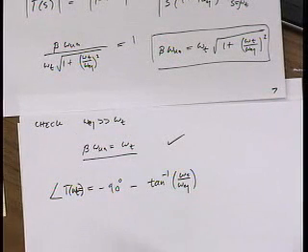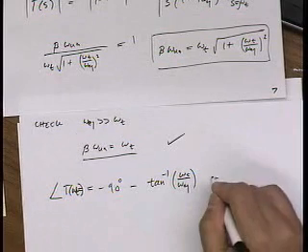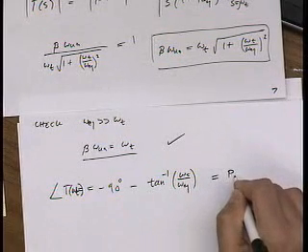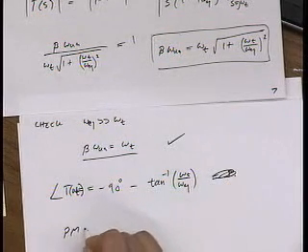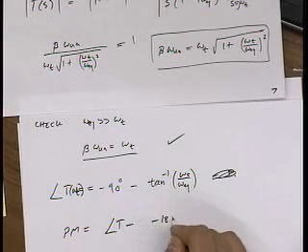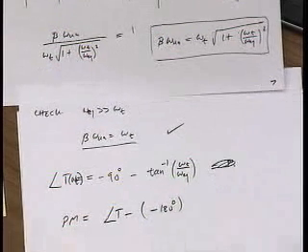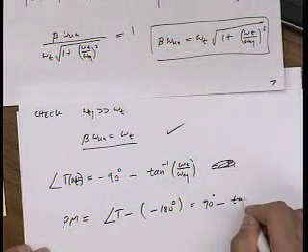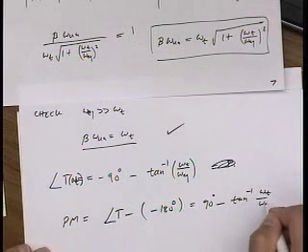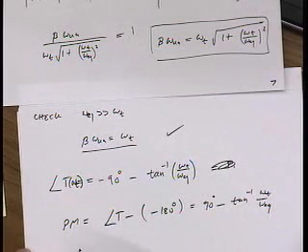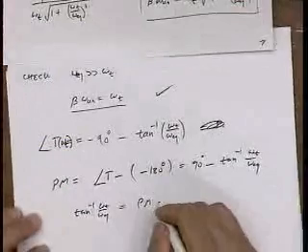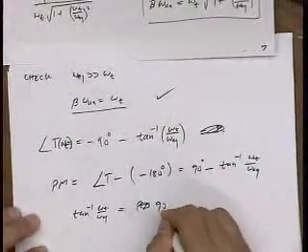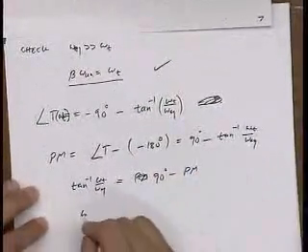Okay? And so I can turn this equation around. I can say this is equal to my phase margin. Actually, my phase margin is how far away I am from minus 180 degrees or plus 180 degrees, the same thing. Because at that point I know I can oscillate, and I can solve this equation. I can say that that's 90 degrees, let's say, minus phase margin, or